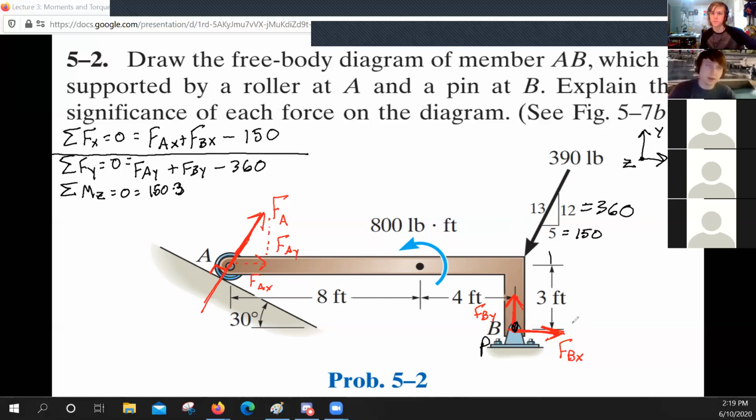One thing, the way that my structures teacher explained it is that if you imagine the line of action extending infinitely, then you need to find a perpendicular line from that line of action to the pivot point, and that's your distance.